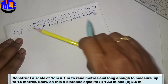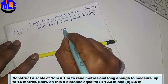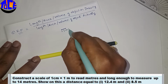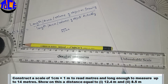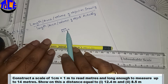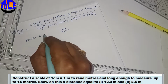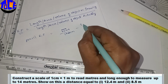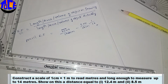Okay. So for example, here you have a pencil. On the sheet, I will represent this pencil like this. So this is my pencil. Here I have represented this pencil with a distance of about 1 centimeter. But actually this pencil is not 1 centimeter, right? If you see here, this pencil is about 16 centimeters. So the actual length of this object is 16 centimeters, but on drawing, I have represented this pencil with 1 centimeter. So my pencil RF will be 1 centimeter divided by 16 centimeters, that is 1 by 16. 1 by 16 is the RF of the pencil.